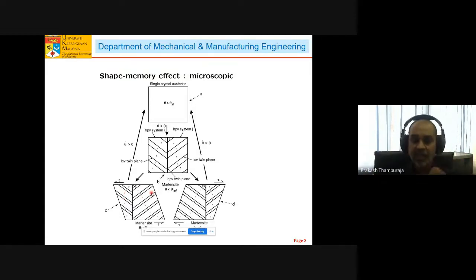They are sensitive to the sign of stress. If you stress it in direction 1, the plates move in one direction. If you stress it in the completely opposite direction, the interfaces will move in the opposite direction. It's very similar to dislocation slip, except that this is twinning. So there are no dislocations here; there are dislocations within the variants, which we're not considering at the moment.